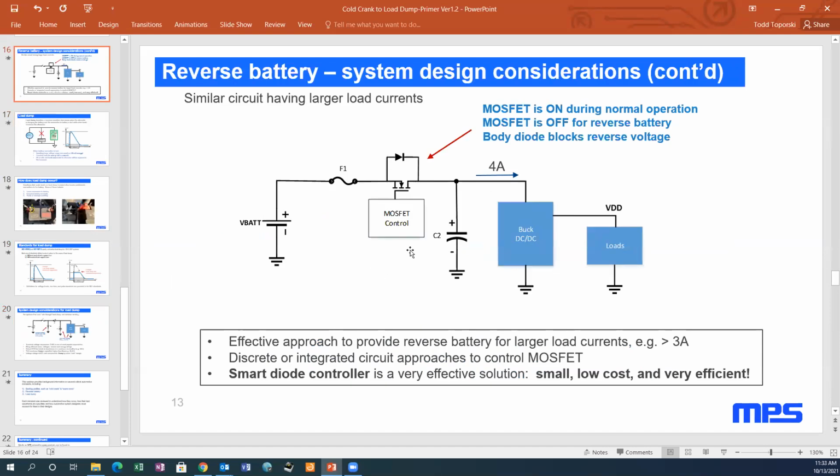Okay, so I think they're referring to this circuit. And this is actually an N channel. This should be an N channel symbol here, if I put it in correctly. Basically, this circuit would need some kind of gate voltage that's created that would be higher than the battery.